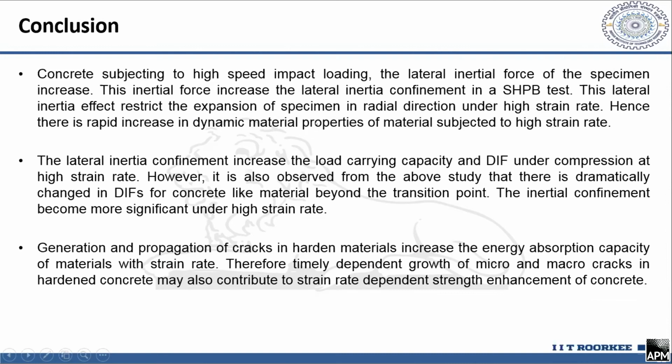But there are very few researchers who define these transition points. Next, the lateral inertia confinement increases the load carrying capacity as well as the dynamic increase factor under compression at high strain rate. However, it is also observed from the above study that there is a dramatic change in the DIF for concrete-like material from the transition point. And the main reason given for that is the inertial force or inertial effect.